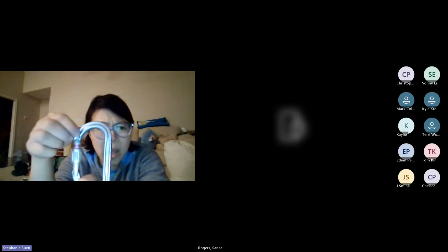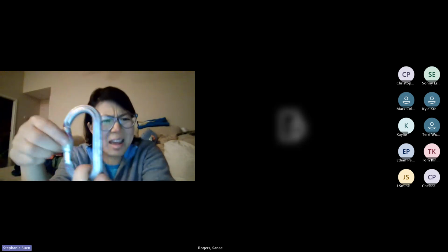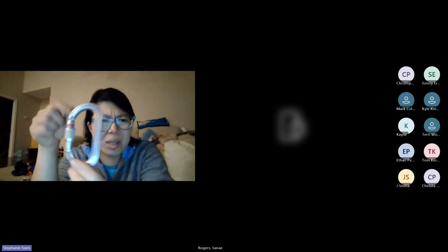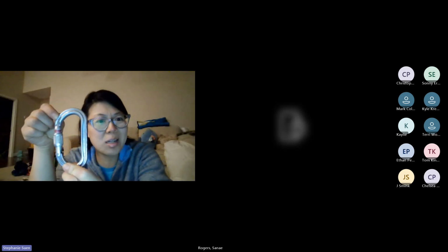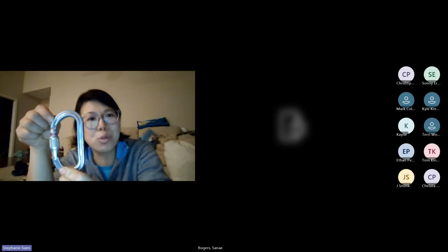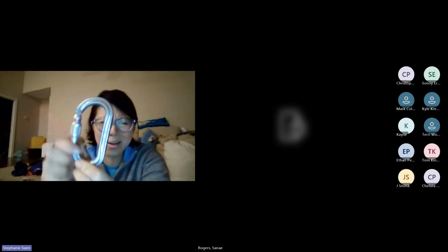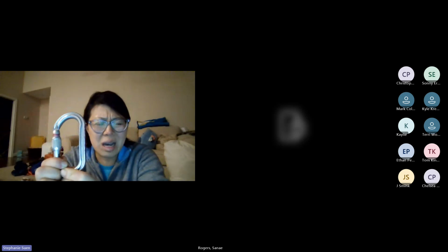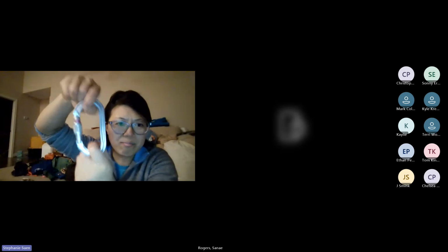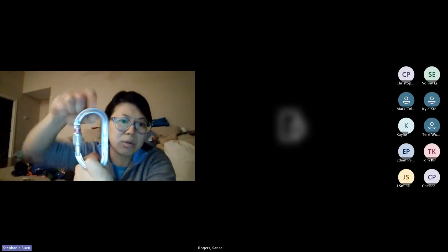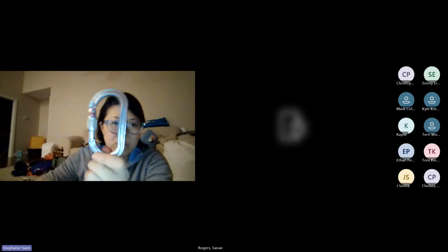In the end, the oval is not good at any one job, but it is able to do all the jobs. So I carry around a lot of ovals because when I'm rigging, this guy can be oriented in a lot of ways and can meet a lot of uses. So that's just a thought there of where you would use an oval.